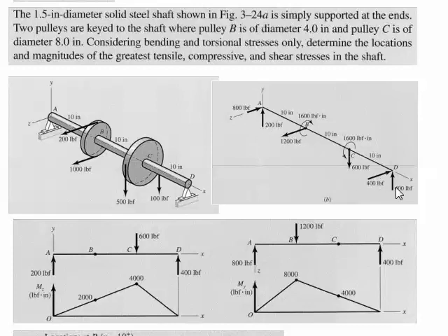After quite a bit of statics, we see the two reactions at bearing A, the two reactions at bearing D, and the load here has been added, these two forces added together into a single force and a torque in one direction. And then these two loads have been added together to give us a single load and a torque in the opposite direction, canceling that torque or removing the torque.